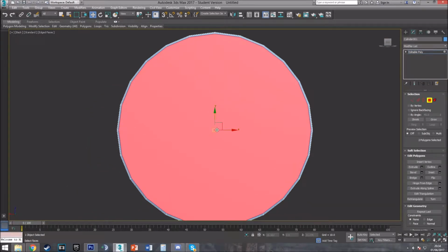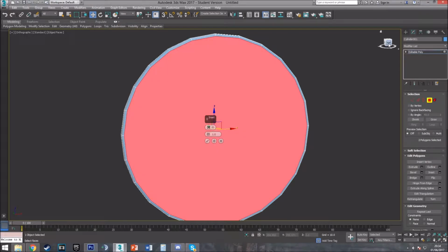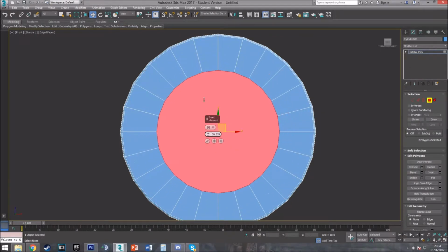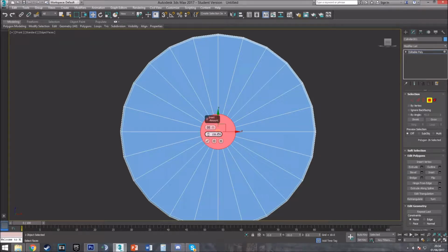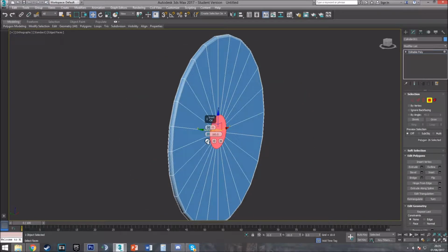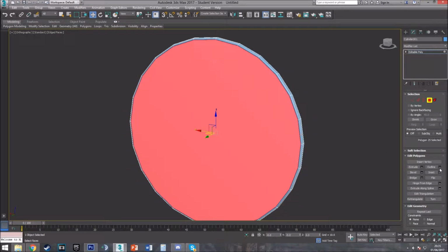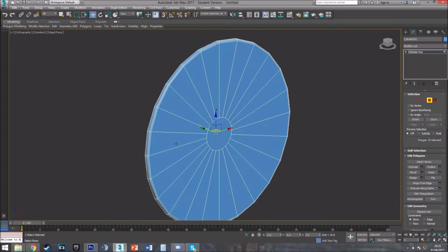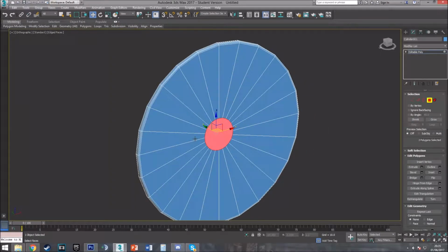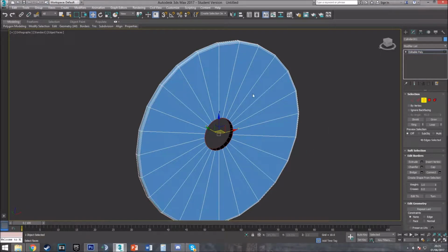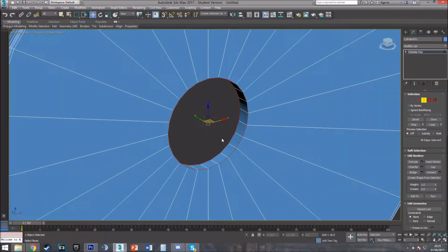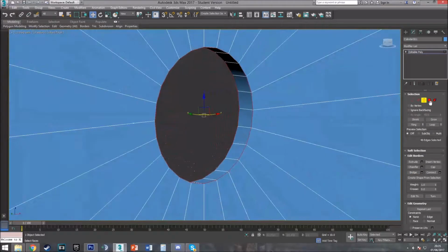and then a vinyl disc has a hole in the center for it to be put on the turntable. So I did this by going into insert, which allows me to create a face within a face, and then just choosing a number I think would be suitable. So yeah, 160 seems good. It's not done on the other side, so it's just boom boom, there we go, done on each individual side. So now I no longer need those, so I can delete them. Bridge these two, so there's no longer the hole there.